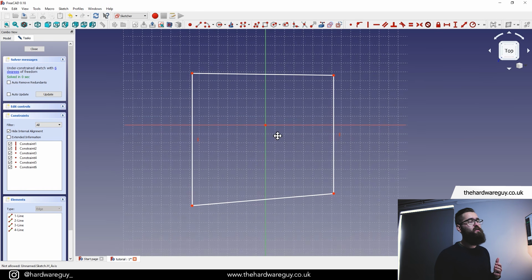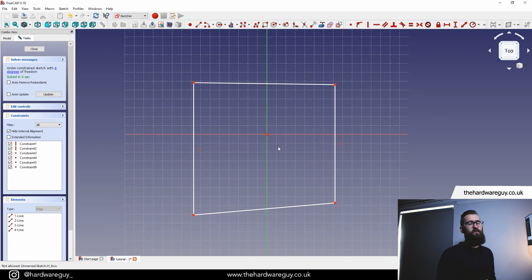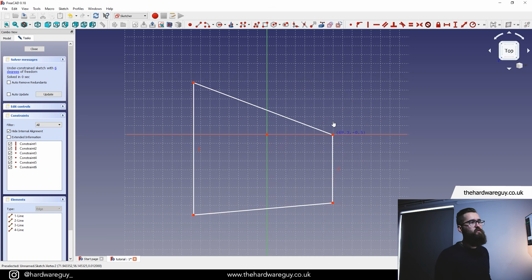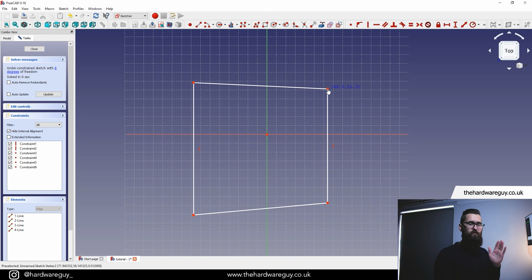So now that we've done our coincident constraint, we can look at some of the other constraints. And if you look at your sketch, you're probably wondering what these little lines are here. So these are constraints. Because these were created as straight lines, FreeCAD already knows that this is a perfectly vertical line and therefore applies a constraint automatically. And let's see what happens if we grab this point here and try and drag it around. Notice what happens. These lines here that are horizontal are adjusting and becoming diagonal, but the vertical line is staying perfectly straight, and that's because we have that constraint on it.